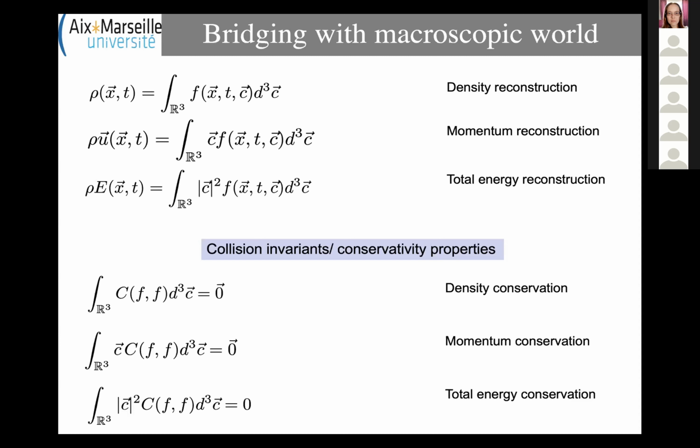The problem is not whether that is possible, because it is possible, since at the very end you recover some macroscopic equations. But the problem is efficiency compared to the Navier-Stokes equations. And in some cases, you had better use the Navier-Stokes equations for sure. And what about boundary layers? So it's not good when there are pronounced boundary layers? Yes, this is what I was talking about during my talk: you can compute it, but the grid will be so fine with LBM that it will be much more expensive than Navier-Stokes for attached boundary layers. These are in some sense disadvantages.